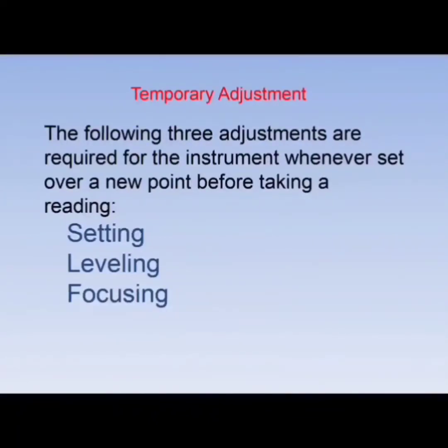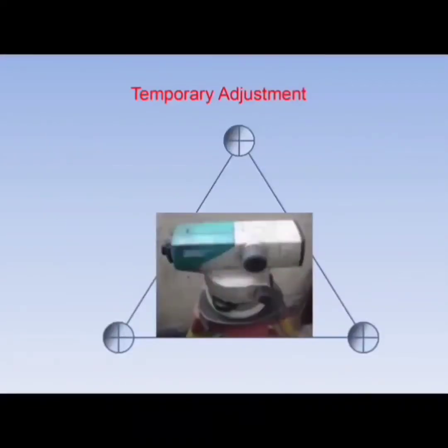Then we have to turn the instrument parallel to two foot screws, and adjust the foot screws such that the bubble comes to the center.